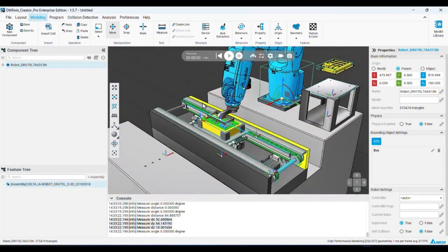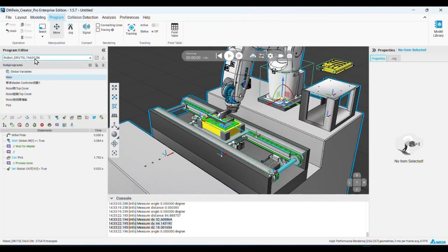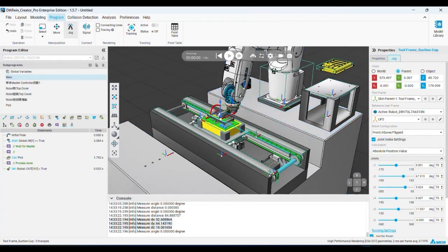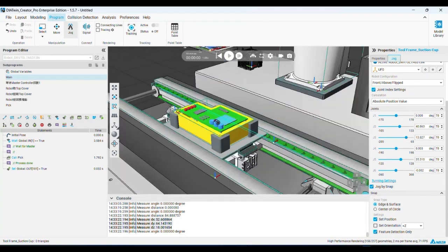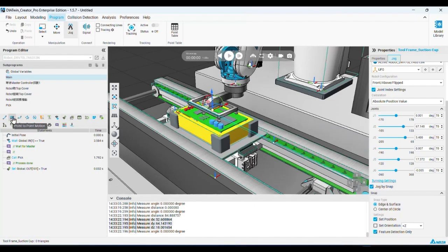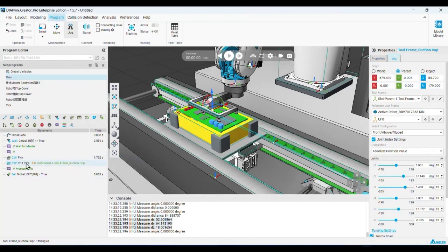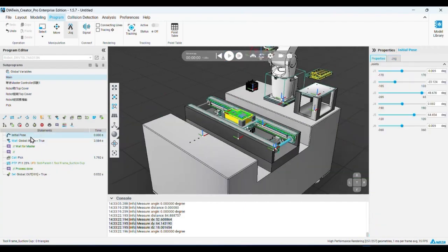So when we need to teach our robot, switch to the robot drop mode. If we need to teach the robot, we can just press maybe here, the center of it, and then 80, right? And then we add another P2P motion, right here after P, and then move to place. Maybe you can take a try. Please remember to reset the robot position.